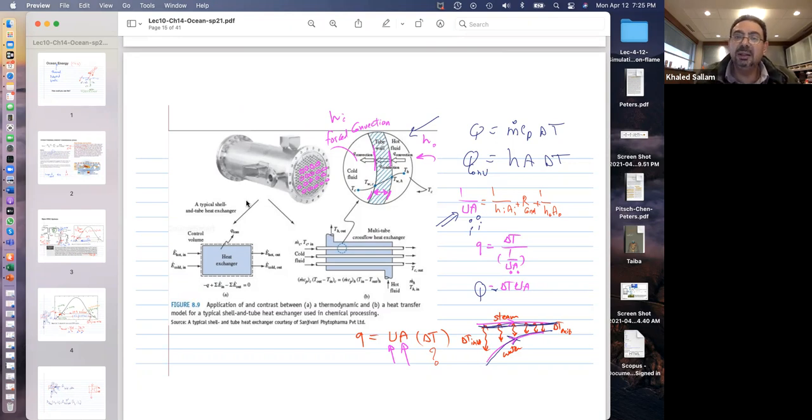And where is the Q added coming from? It's coming from the heat exchanger that will use the seawater to heat our ammonia, butane, propane, whatever. So we need a big heat exchanger, right? We need to know what's the calculation for that heat exchanger. So the one and only equation in heat transfer that everyone should remember after a heat transfer course is Q is UA delta T.